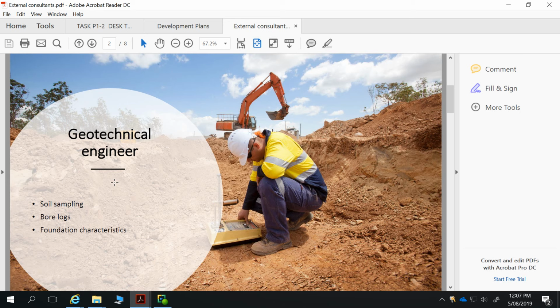And the other reason for that is, if you don't have main sewer there, you're on a septic system. You do your minimum 3 soil samples where you're building your house, and then also think about where you're doing your septic system. You're going to do about 1.5 to 2 metres deep there, to see how that effluent is going to soak into the soil. For on-site wastewater, the way we deal with it is letting it soak into the soil, because that way the microbes and everything can deal with it. It feeds trees, etc. That's the way we deal with it, but we want to see how that can happen.